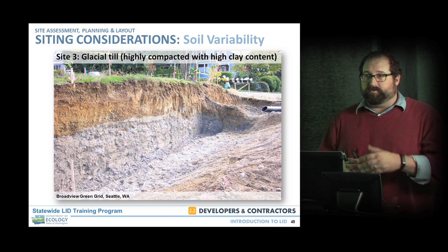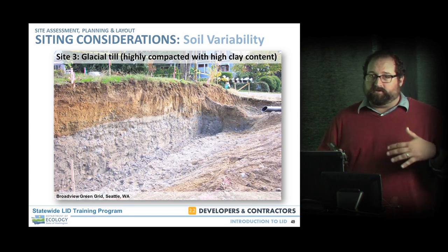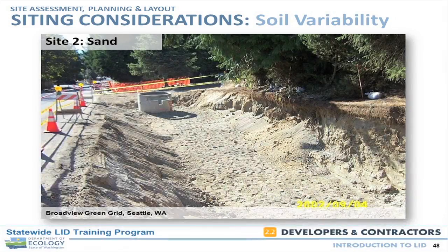So that goes back to the fine grain and how much infiltration testing you need to do. If you are siting bioretention facilities, once you've gone through that initial design process and you know where a facility is going to be, make sure you're definitely at least testing there, so you know that the performance you're estimating is going to align with that.